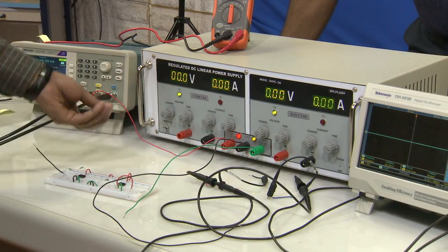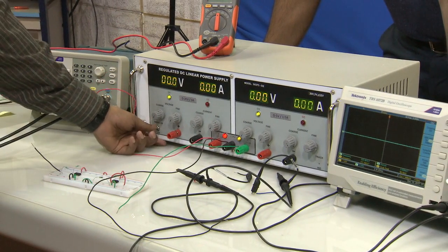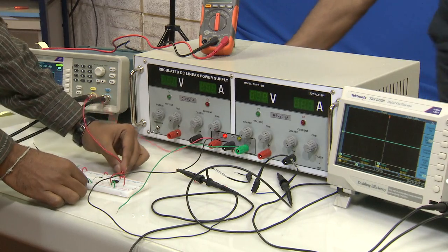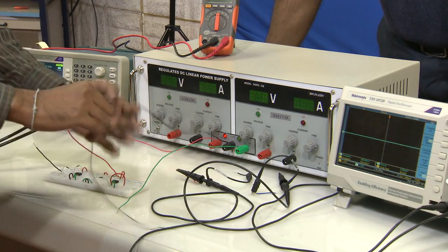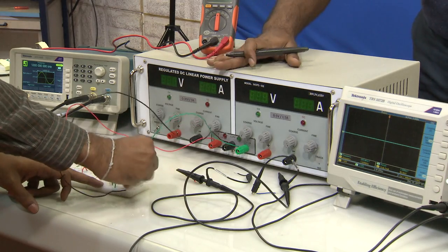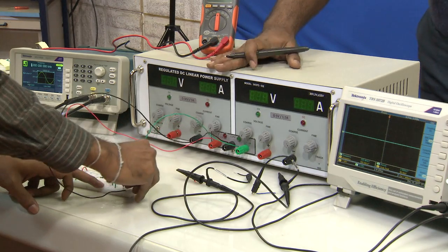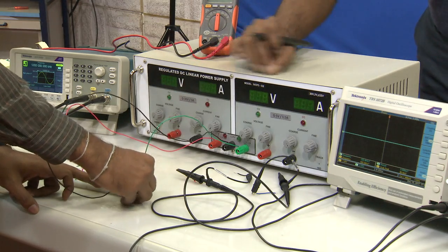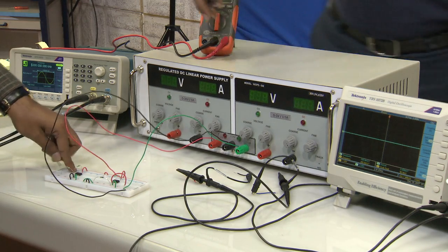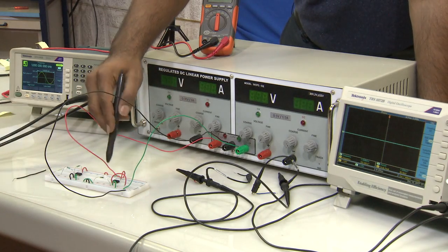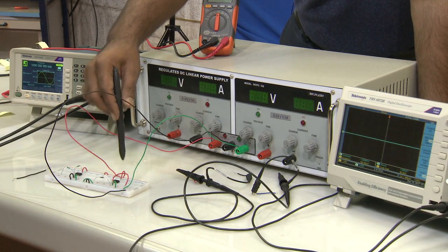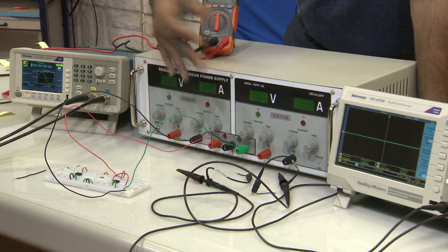So, plus 15, and now it is already on. So, we have to first switch it off. Now, you apply plus minus 15. It is already there; actually, you have to switch off this one also, but I am not doing that, that is fine. See, there is no voltage coming from the DC regulator to the circuit. You do not have to take this much of a chance. Be extremely safe when you perform any experiment. So, we have now connected plus 15 and minus 15 to the operational amplifier, that means pin number 4 and pin number 7 are connected with minus 15 and plus 15 respectively.